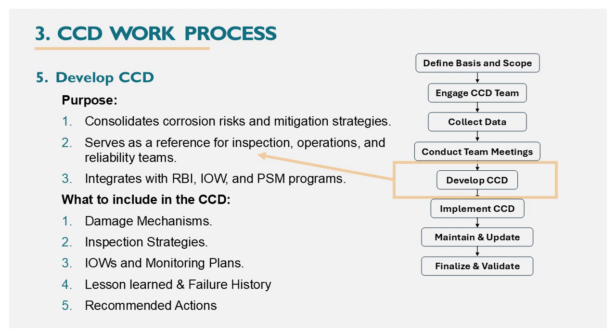Number 3 to be included in the CCD is IOW monitoring plans. These are to define critical process variables: temperature, pH, chlorides, sulfur. Set IOW limits: critical, standard, informational. And set the alarm response actions and monitoring methods.